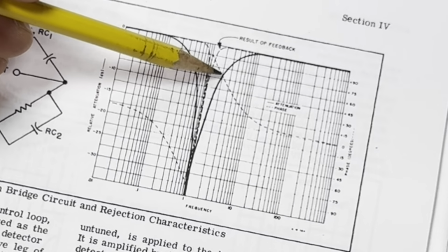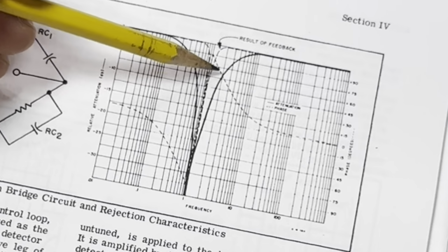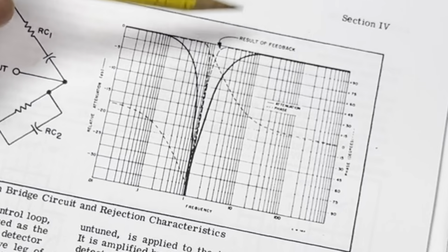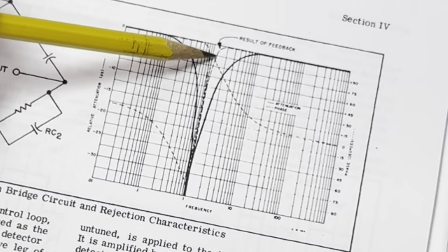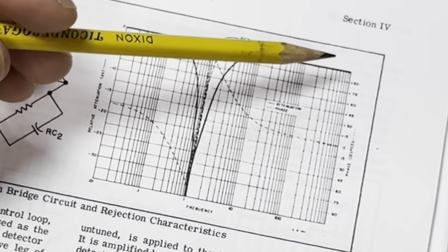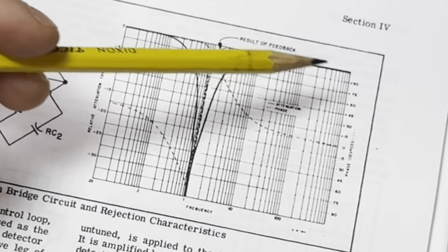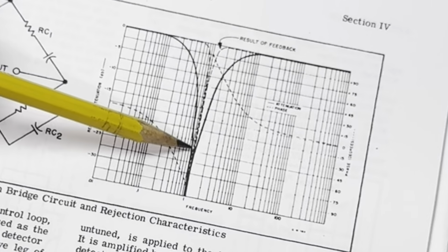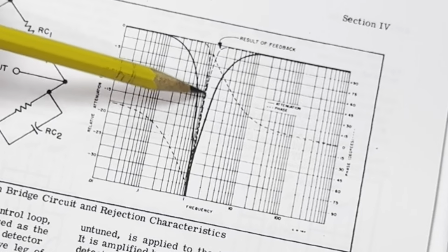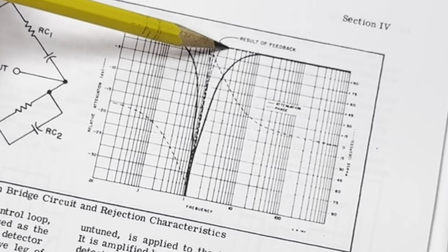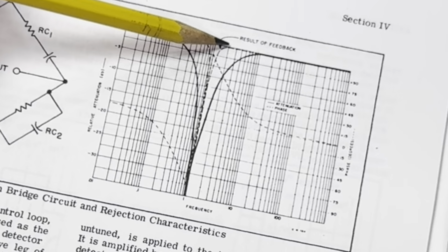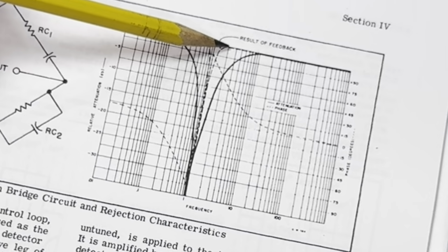So how do we adjust for the attenuation of those harmonics? Well, we use feedback in our notch filter. And that's what this dotted line shows here. So when we apply the appropriate levels of feedback to our notch filter system, what happens is we tighten this notch and we make it very, very narrow to the point where our second and third and fourth and so on harmonics are not affected, or are not affected significantly enough to alter our measurement.